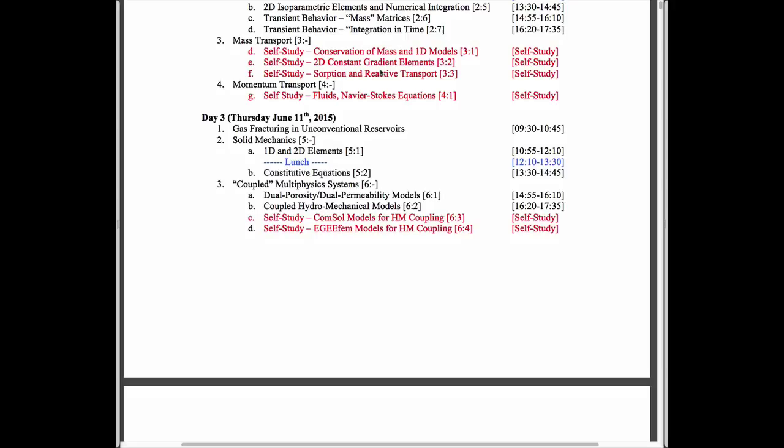The only difference between those two systems is that in fluids, the constitutive law that we use is actually Newton's law of viscosity, tau equals mu dV/dx. I guess I write it on my page, so that shear stress is equal to mu times dV/dx. And in solid mechanics, we use the model that stress is equal to the constitutive model times the strain.